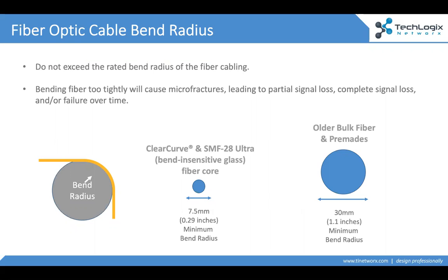And one of the problems with fiber isn't necessarily that it snaps. In a way, you're lucky if it snaps and it's fully broken, because now you know where it's broken and you know you can replace it. What tends to happen with older fiber optic cables is you get microfractures, meaning that the cable, just like a windshield, will get a chip in it. It'll get a little crack in it. But over time, that crack gradually expands. The cable gradually falls apart. It's incredibly hard to troubleshoot.